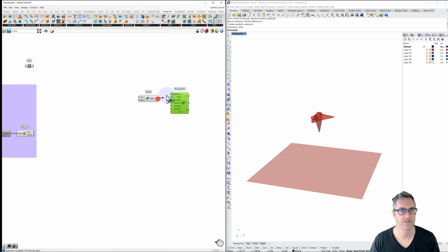Here's our bouncy solver. Those merge objects will be our goal objects. We want to have our iterations. I've tended to use 50 for this in the past. I'll set this with a small panel.